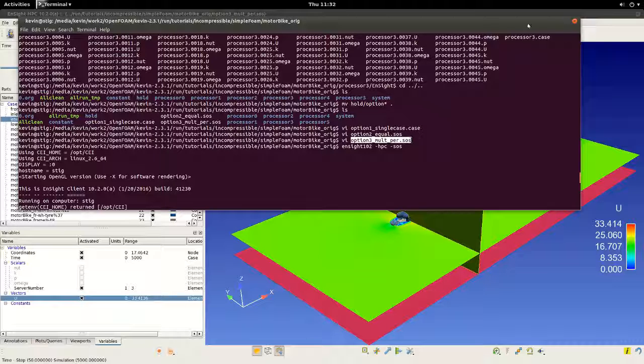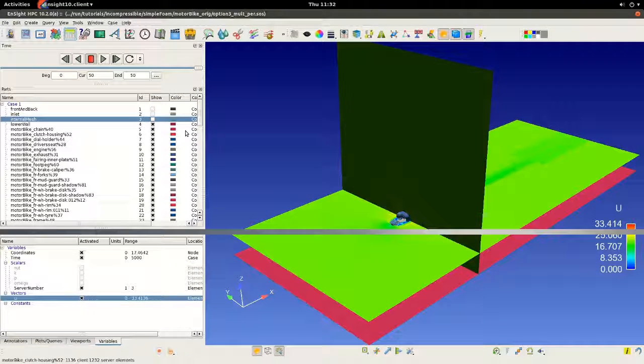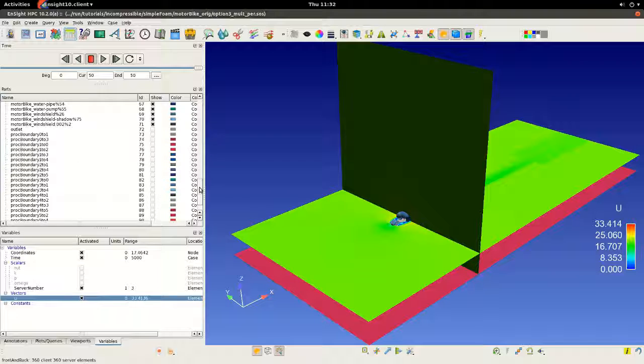The new capability in EnSight really is to allow a global parts list, as each of the different partitions have their own part list for their own parts in there. And so the new capability in EnSight 10.2 is to combine those local part lists into one large merged global part list that's not duplicated, so that in EnSight we see one session here, and we see one coherent set of parts within the session of EnSight.